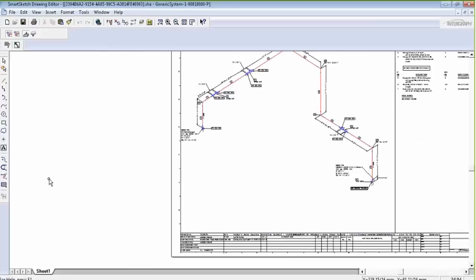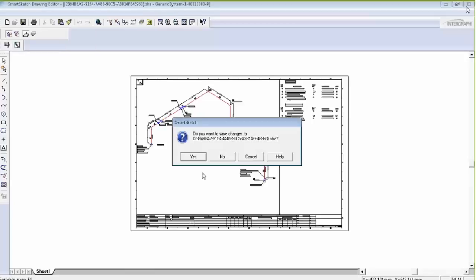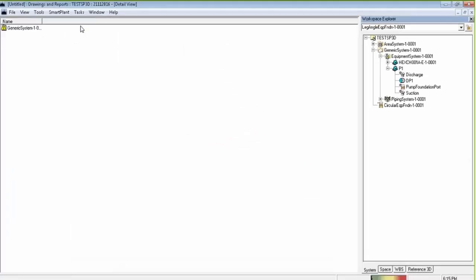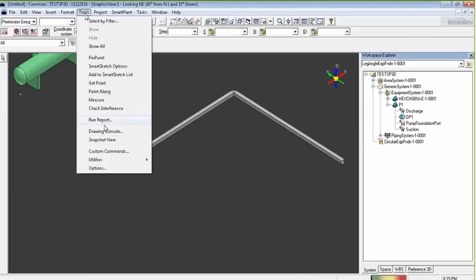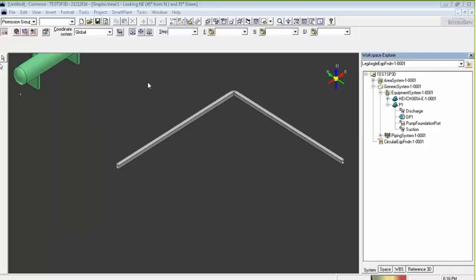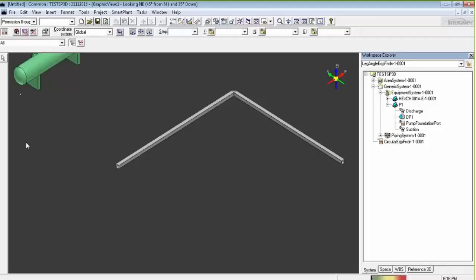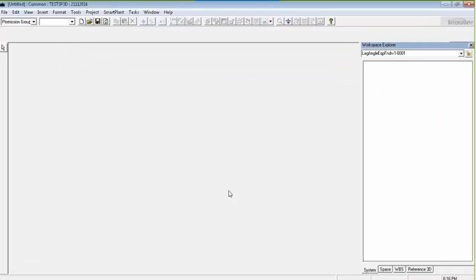Okay, everything is in detail, and this one you can file, save as image, save as PDF as I told earlier, and also save as .dgn or .dwg. Save as, you can see here, MicroStation, AutoCAD, all formats are available. So for the deliverable part also you need not spend much time. You also need not save in the software, it is auto-saved to the database. If I exit today and open tomorrow, it will be available. It's not a file-based system, it's a model-based system.